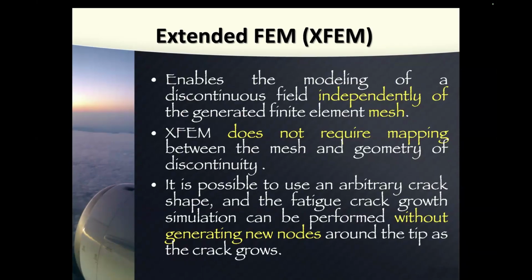In XFEM, you don't need to map the mesh between geometry. I told you, in Franc3D, when you create a new crack, it's new shape of geometry. So you need to remesh that again and again and again and again. In XFEM, you don't need to do that, okay? You need one mesh, and that mesh will be used through the whole simulation, okay? So the number of nodes is not changing during the analysis.